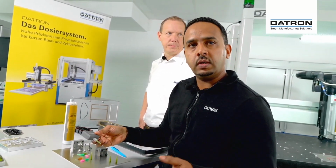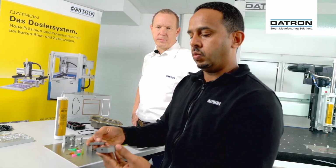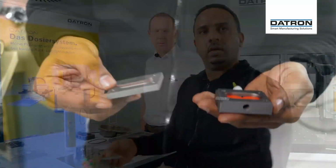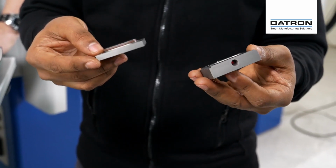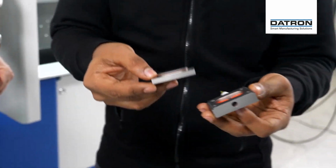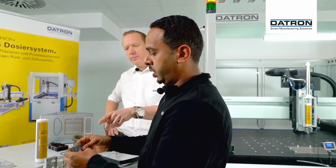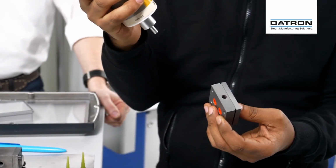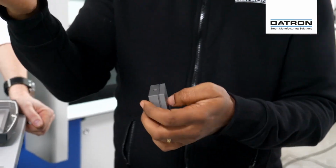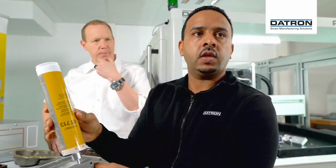In case of cleaning, we can disassemble it easily. When you have a material which cures under room temperature or moisture, it needs to be cleaned every day. If you have a simple pump that you can easily disassemble and clean, it's a big advantage for you in the new process. When the material is finished, the pump is finished. There we have a cartridge, in this case a 310 milliliter cartridge. The cartridge adapter will be put on, placed into the machine, and that's all you have.